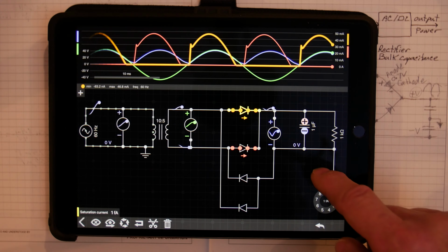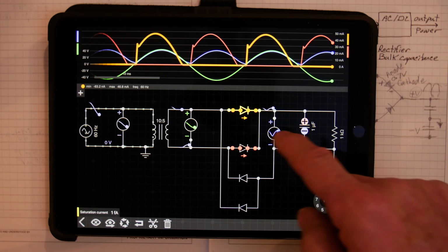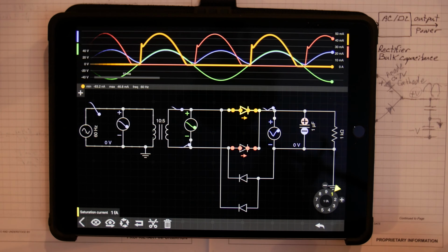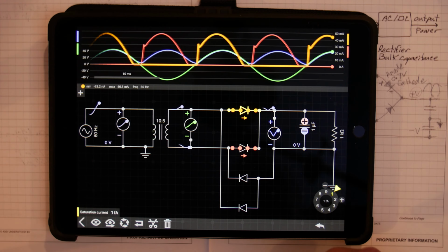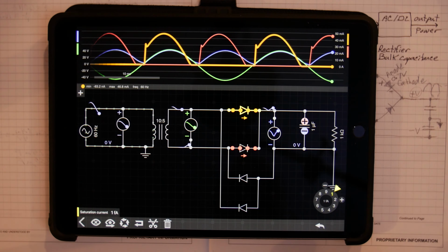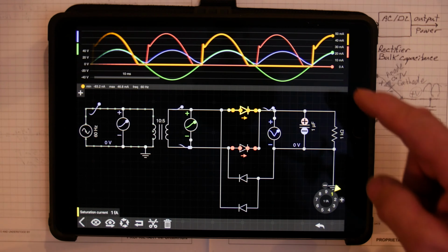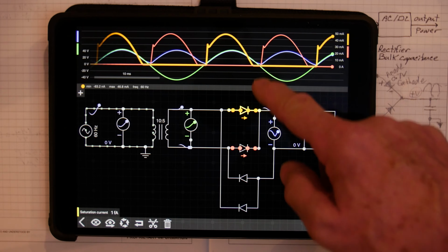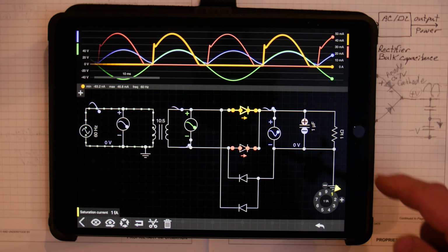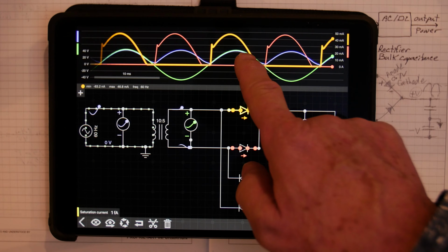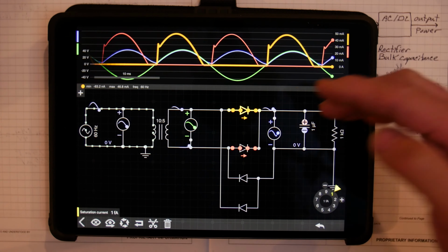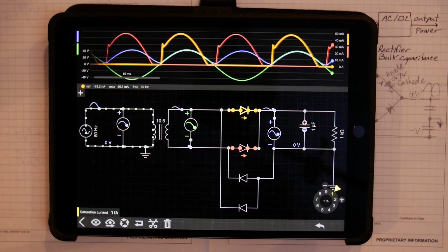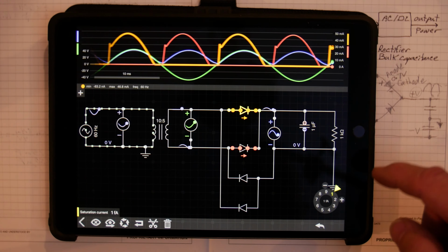So the peak currents in these is about 46.8 milliamps. Now that was about the same as it was with the half wave rectifier, right? Even though we're getting double the charge cycles. Why is that? That's because our capacitor is being discharged every cycle, so it has to start over. So every one's the same. It's not until we start keeping that capacitor above ground, where we don't have to start from zero, that it really starts to make a difference on the charge current.